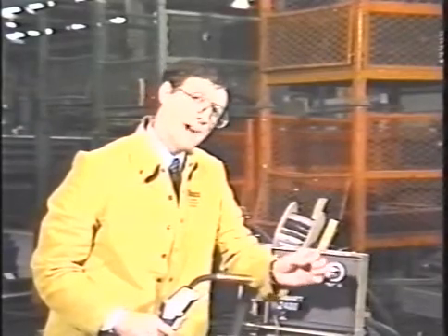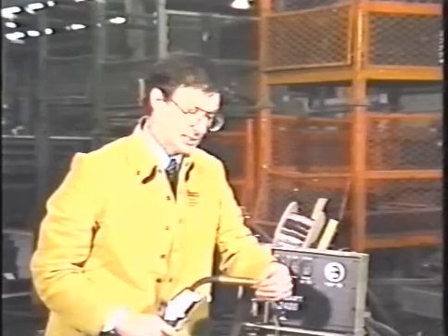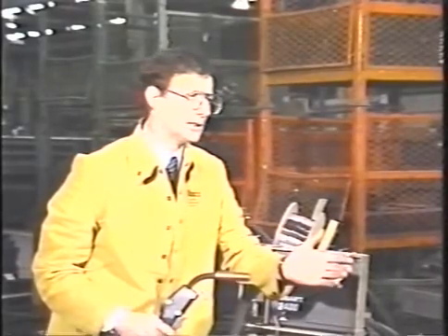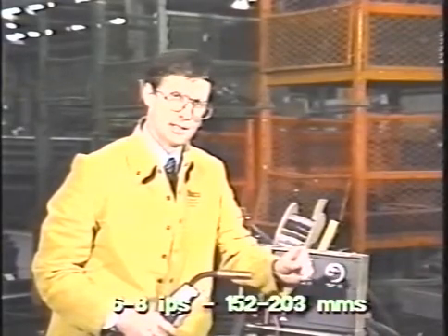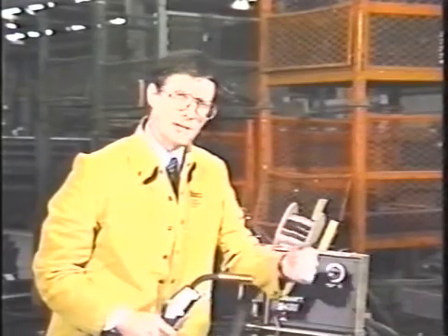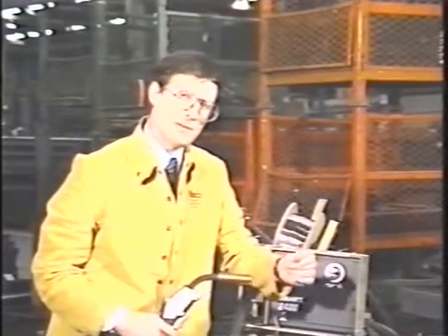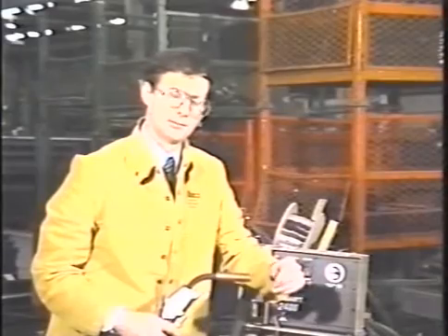You know, an 035 wire in spray transfer is fed at almost a feed rate of 10 inches a second. Now with an 045 wire, the feed rate would actually be in the range of 6 to 8 inches. The slower the feed rate through the system, the less feed problems in general.